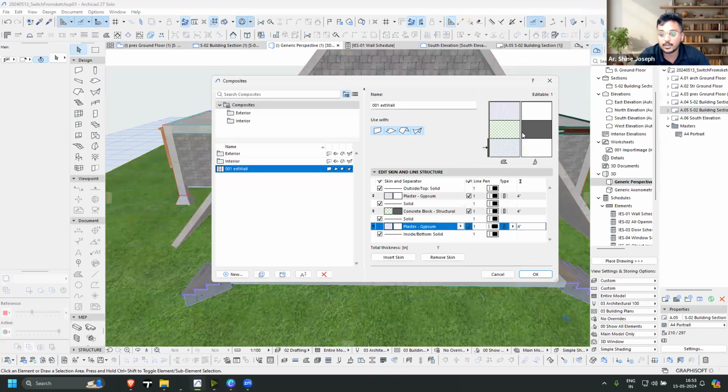Now I just have to specify the thickness. Both the external parts are finished, and both of them at the same time have to be thinner. If I go for the external wall, I can go for, let us say, 1 inch, or internal ½ inch. It's just up to us, whatever the value is, you can always do that. And this one, let's go with 8 inches, the center part of it, the core part of it. So we created a new one. You can also assign it to only the wall.